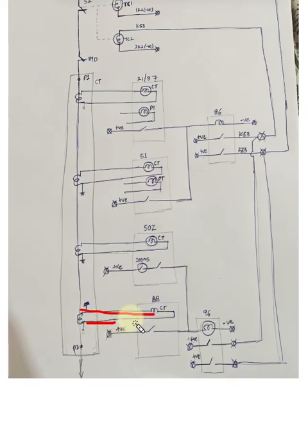Similarly, all the feeders are fed to the bus bar relay, to its current coil, and when the bus bar relay operates, when there is a differential current, when the incoming is not equal to the outgoing current, and there is current in the differential coil, its output contacts operate, and it trips the 96 relay, which in turn trips the breaker.